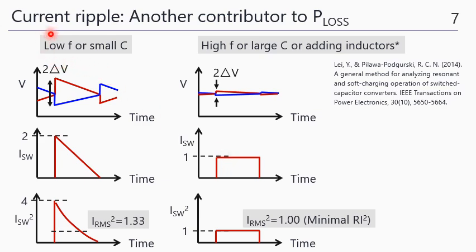So this is the case when the clock frequency is very low, or the boosting capacitor is very small. Then the charge transfer affects a significant voltage change per cycle, or in other words, the current transferred from one capacitor to the second capacitor has a very high height.